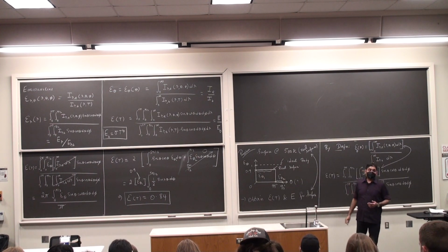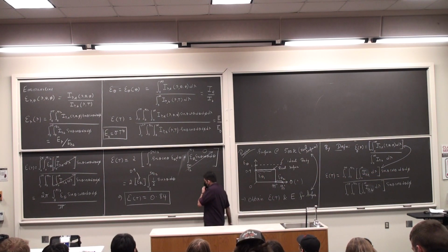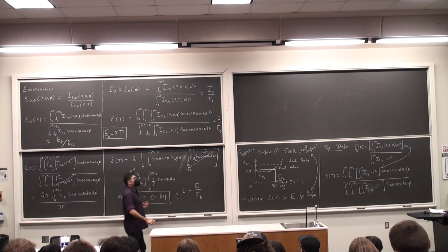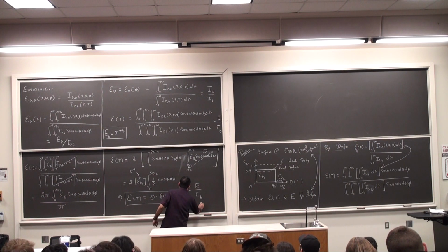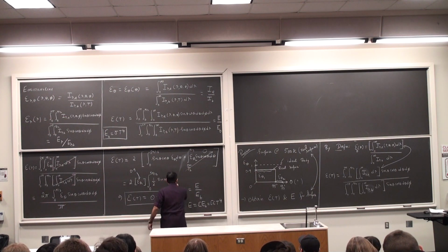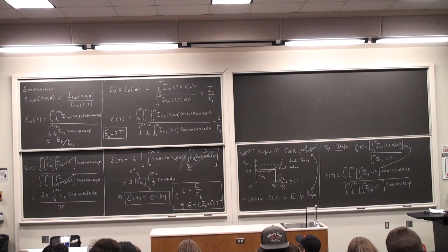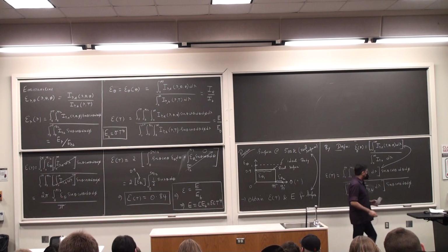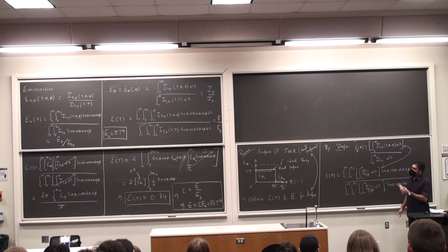And if I have to calculate the total emissive flux or the total emissive power, it is just sigma times epsilon times T to the power 4. So epsilon is E by E suffix b, so E is E_b times epsilon, which is sigma epsilon T to the power 4. You can perform the substitution. Sigma is your Stefan-Boltzmann constant. You're going to get to know that constant very well in the next couple of lectures. We're going to solve some numerical problems. T is 500 Kelvin. Epsilon is 0.84.